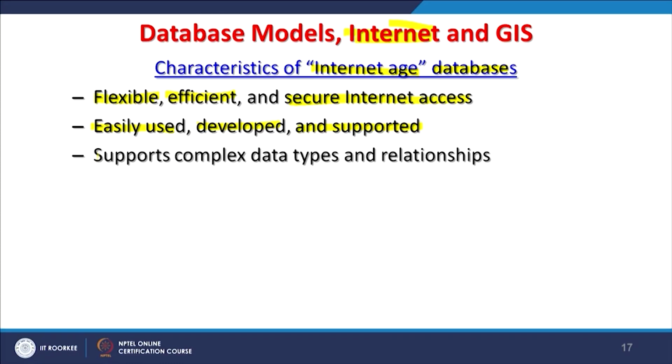Now it also supports complex data like Google Earth does, not only the digital elevation model and satellite images, but a lot of other data sets. And after doing your own data processing, you can paste your data over the Earth and check the georeferencing. For georeferencing purposes, we can employ Google Earth: we can collect ground control points from it, and after doing georeferencing we can paste that image on Google Earth and see whether it fits with the Google Earth image database or not.